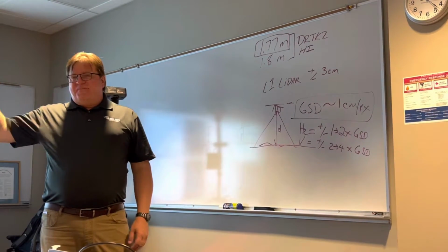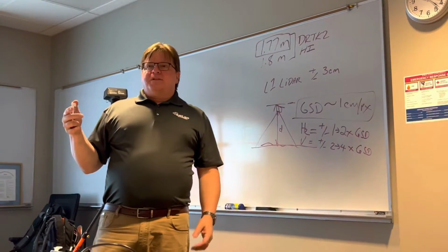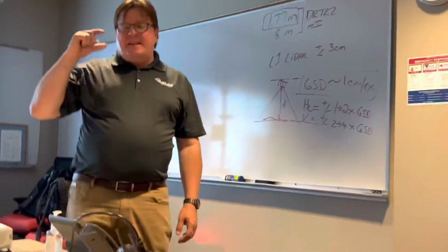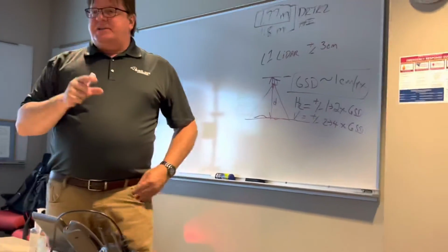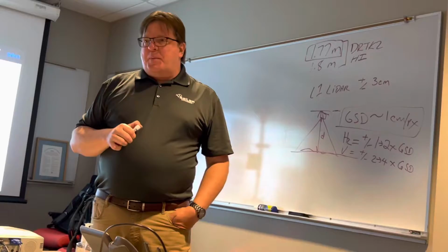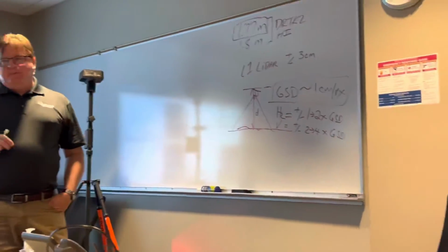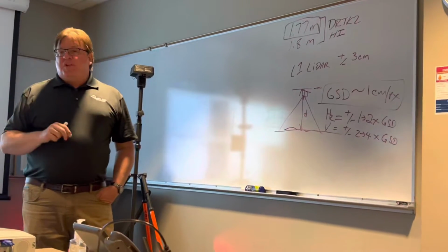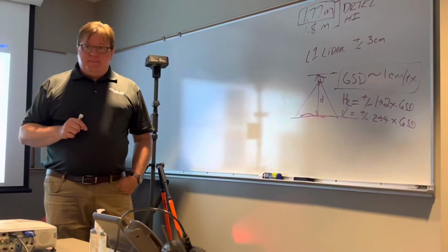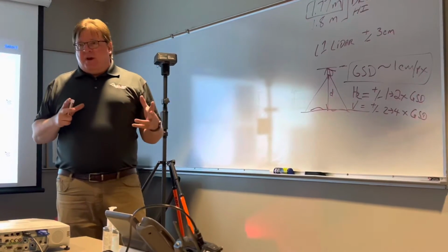It's like the 15th decimal point, it doesn't really matter. So we're talking plus or minus, it's basically a fixed accuracy of plus or minus 3 centimeters, plus or minus 5 parts per million, and at 200 feet, that's nothing. Basically independent of your altitude and speed. So what we're going to shoot for with the LiDAR instead is density. The lower and slower we fly with the LiDAR, the denser our model becomes.